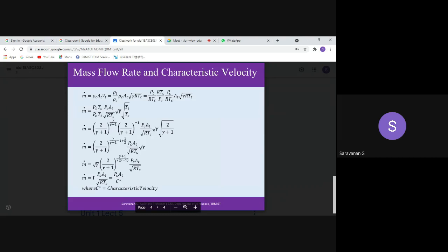The thing is very simple. You should have the basic thermodynamics knowledge. You should have the isentropic flow through nozzle relations, and the idea of what the relation will be if Mach equals 1, and what it will be for any Mach number. So you can have a stagnation and static relation. Stagnation corresponds to the chamber, and static corresponds to any state, maybe the nozzle exit, nozzle entry or diffuser exit. But in our case, it is a nozzle.